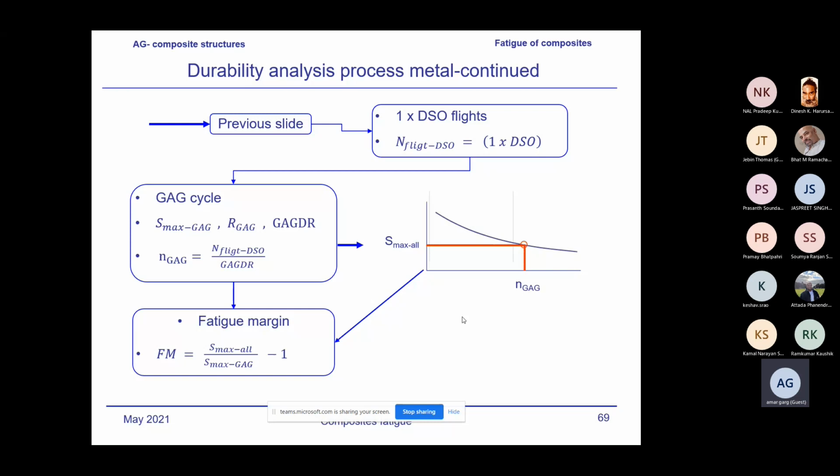There are complex methods developed by Boeing. They are all standard in the handbook with all the parameters. In fact, from the experience of like 50, 60 years, they have generated all those factors which they have used in order to develop all these reliability and confidence factors, process factor, everything. And then finally, they develop the SN curve factors to determine this life. So this is, in summary, a general procedure in order to determine the durability of the structure.